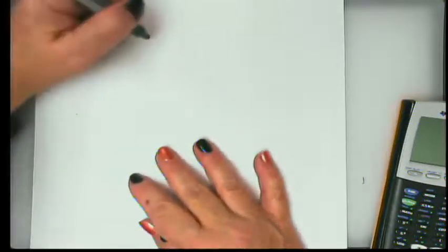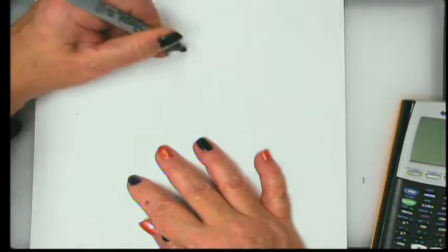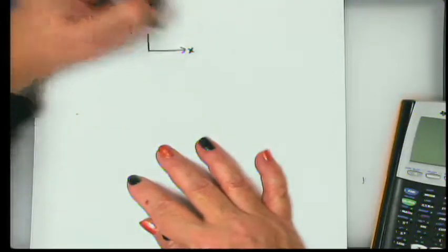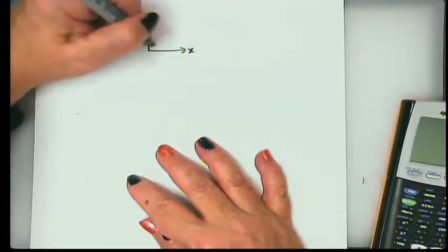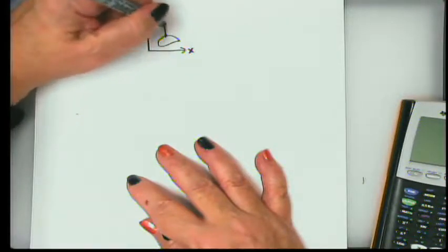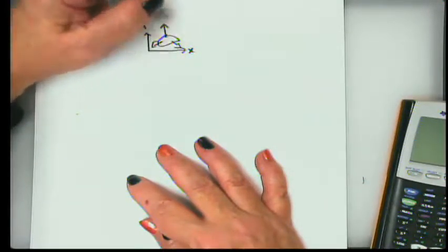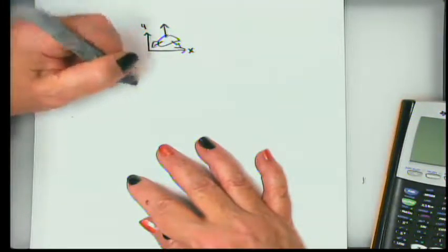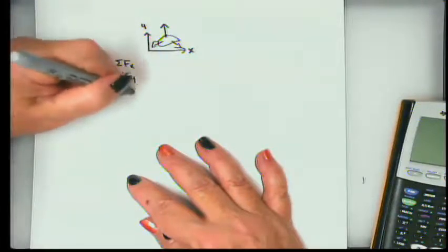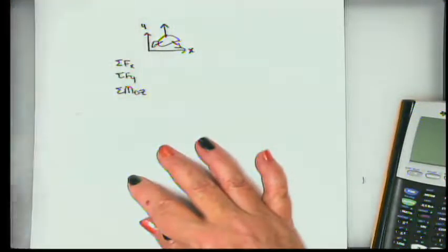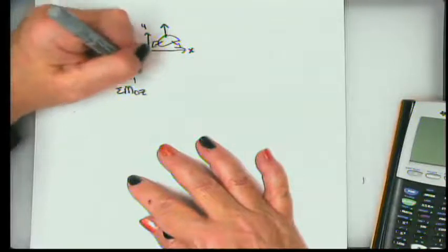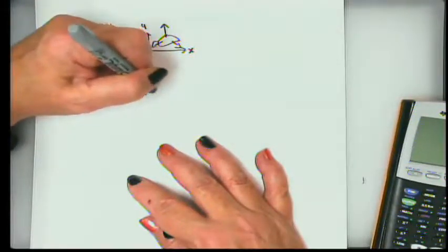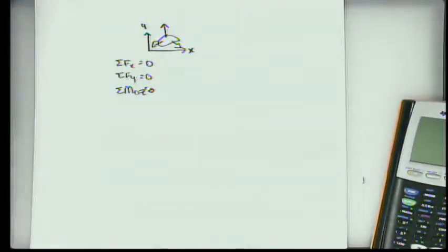Okay. Now, with equilibrium in 2 dimensions, I'm going to talk about this for just 1 second. If all the stuff is going on in the XY plane, we have a rigid body, we have some forces acting on it. We know that the summation of forces X, summation of forces Y, and in this case all the moments about any point are going to be in the Z direction, and that in order for equilibrium to occur, those 3 conditions have to be met.